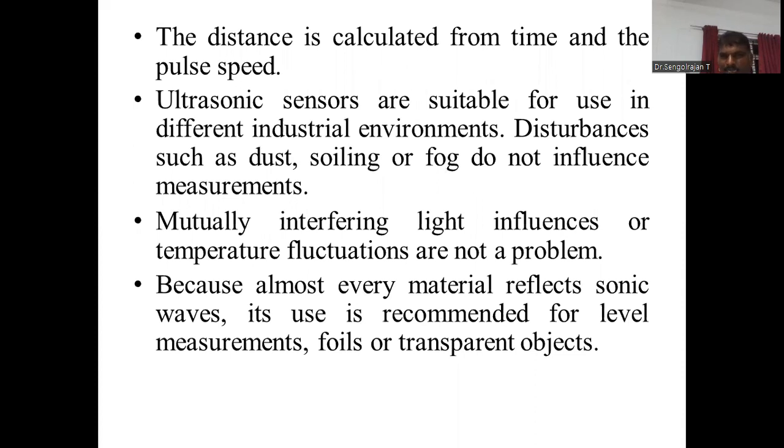The distance is calculated from the time and the pulse speed. How do you calculate it? If you are sending the sonic pulse to the object, from the source to the object and again from the object back to the source, the time required and the pulse speed that it travels are used. Ultrasonic sensors are suitable for use in different industrial environments, where disturbances such as dust, soiling, and fog do not influence the measurements.